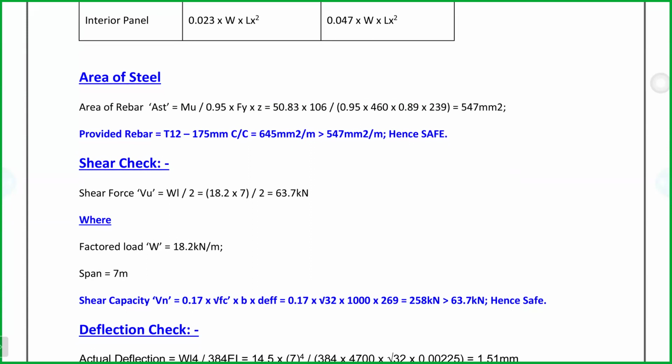I'm not talking about the shear reinforcement. In a slab, you don't have any shear reinforcement except the punching shear layers. There won't be any kind of shear reinforcement. Even in both directions which you talk about, it is all main reinforcement only. The shear reinforcement comes only to satisfy the punching shear, to satisfy the shear, either one-way shear or two-way shear. This is completely related to shear calculation.